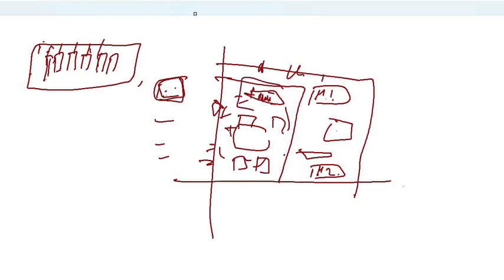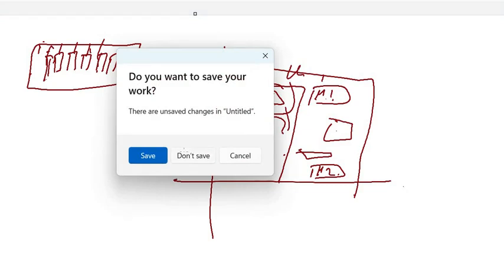But when you add guard rings, that eats up some space. So whenever you are giving an area estimation, always keep in mind: do the required matching along with the dummies, place the guard ring, and then give a proper location to it. That's how you do it for other modules as well.